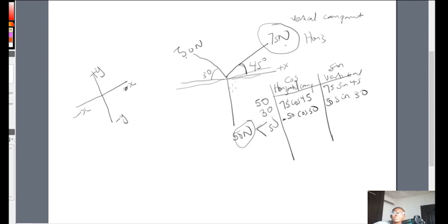So we go to the other side, which is the 50 Newton, the last one. Now this 50 Newton is here, right? So to the vertical, have you seen it? You can see that it's 90 degree. So that will be what? 50 cos 90 for the x-axis because it's along the positive x-axis. Then minus 50 cos 90. Why? Because it is along the negative for the y-axis. Don't forget, it's only the angle that is inclined to the horizontal that we use.